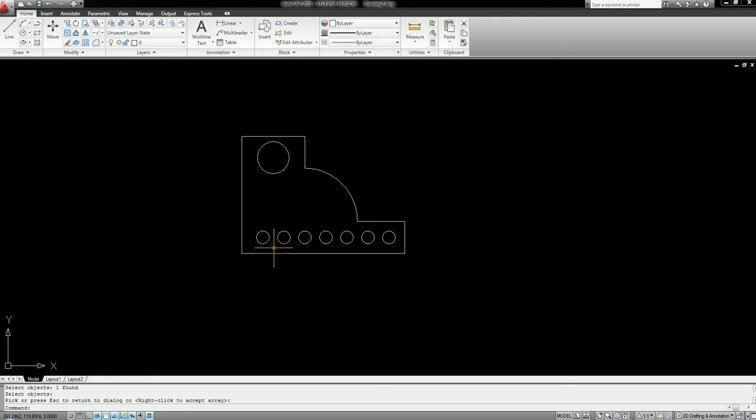Now I need to go in here and figure out this other interior portion. The easy way for me to do this is to start by offsetting this. So I'm going to go back to that offset command, 20, enter. Then I can just left click and bring that down to right here. This is going to give us a good start point.